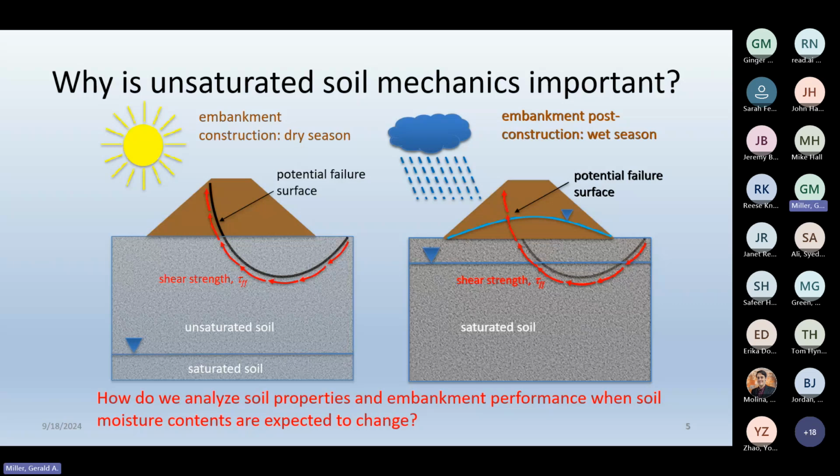But we also need to be thinking about volume change behavior, because that's important as well, especially in unsaturated soils. We've done a lot of research on wetting-induced compression of compacted soils. And compacted soils are susceptible to significant settlement. If the embankments are high enough and the stress states are high enough, you can get this wetting-induced compression in the lower regions of the embankment, which can lead to significant settlement.